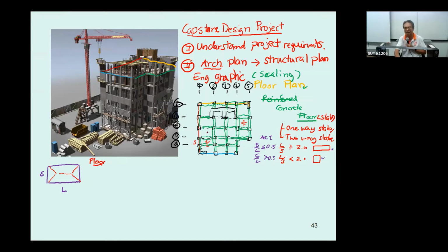And then what you need to set now, you set for the floor or the slab, you consider the area, you consider the ratio, and then you set the floor as slab 1, slab 2, whatsoever. You also need to set the slab, and then you will transfer the load on the slab into the beam. Now it depends on the area. That is your beam taking care of the load distribution area. And you set the name of the beam to be B1, B2, whatsoever.